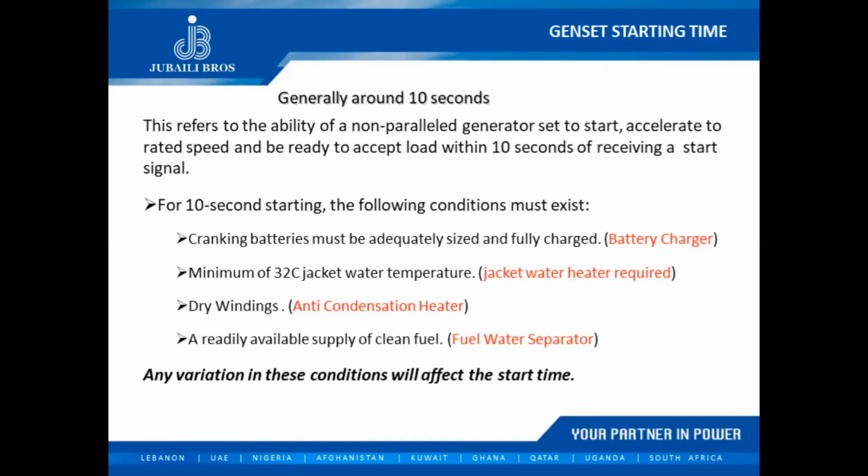Typically, when we're after this 10-second starting time, we'll have to introduce some starting aids. We need fully charged batteries, so we'll add a static battery charger. A jacket water heater would be there to keep our coolant at minimal temperature. An anti-condensation heater ensures that our windings are dry.